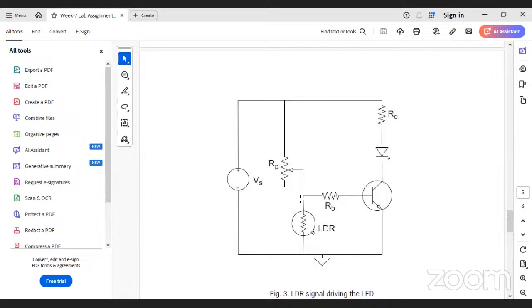Actually, having a constant DC voltage will also have glitches with the repeated sweep enabled. So maybe we could try with 10 seconds of repeated sweep. It will be fine, because the glitches will be there even for constant voltages. I have measured it using the oscilloscope available in my college.